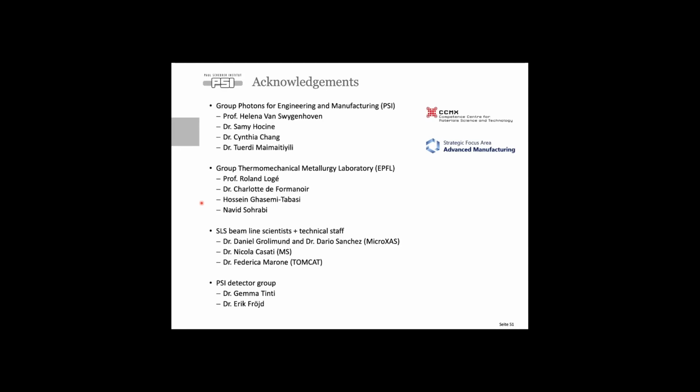So, of course, with EBSD, you see that the cracks are mainly intergranular, and this is typical in these alloys. So my first point would be, could you try a single crystal experiment, or big crystals maybe, with a controlled orientation of the two single crystals that you have in contact? It would be nice to see the effect of the grain misorientation of your big crystal, to see the propagation of the cracks, whether or not it happens, and what is the influence of the orientation of the grains.